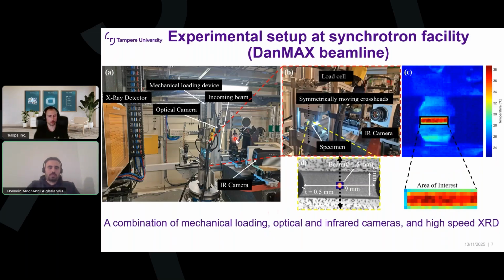This is the most important slide in my presentation. You can see here the inside of the hatch at the DanMAX beamline. It took us half a day to set up this experiment, and there are many challenges, for example the synchronization. You should synchronize the IR camera, optical camera, the XRD detector, and also the incoming beam. You can see here the detector, the beam coming through here, the optical camera and the IR camera.